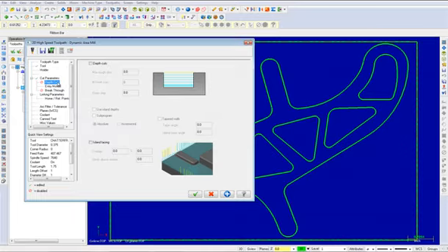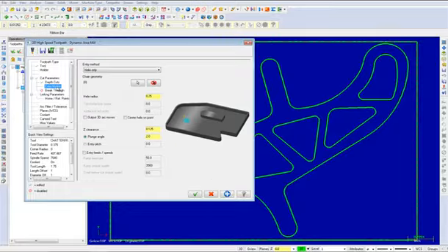Enable this option and input a max rough step of 0.75. Also, input a finish step value of 0.05. From here, select the entry motion. Change the entry method to profile as shown. Also, input a Z clearance value of 0.125 and a plunge angle of 2 degrees.